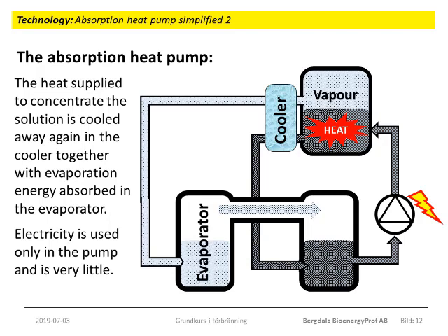To stay away from the equilibrium, the solution in the absorber, in the energy absorber, must be maintained at a low concentration. So this solution is pumped to a distiller where heat is added to vaporize the solvent. Using the example from the previous slide, this is to say that the ammonia is boiled off. The dilute absorption liquid, almost pure water, following the same example, is cooled and returned to the absorber. The solvent vapor, ammonia, is cooled until liquid and returned to the evaporator.